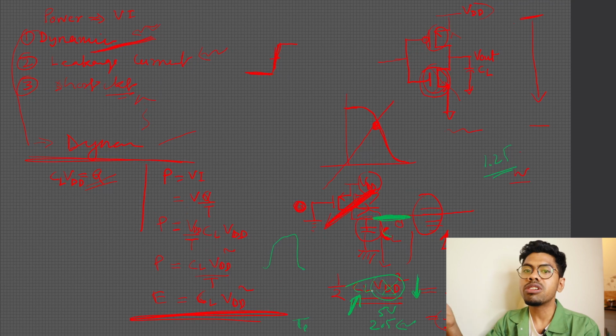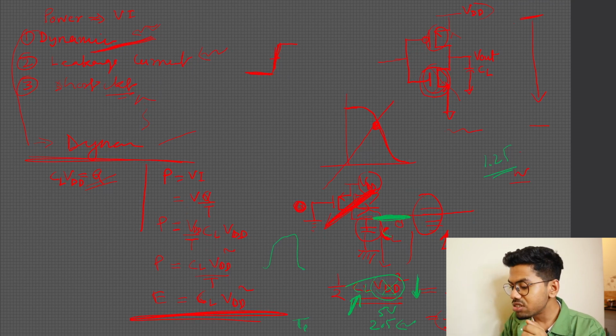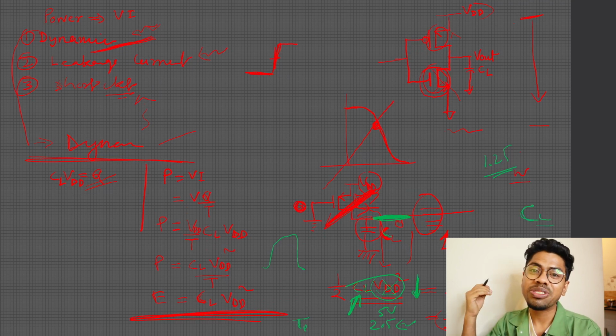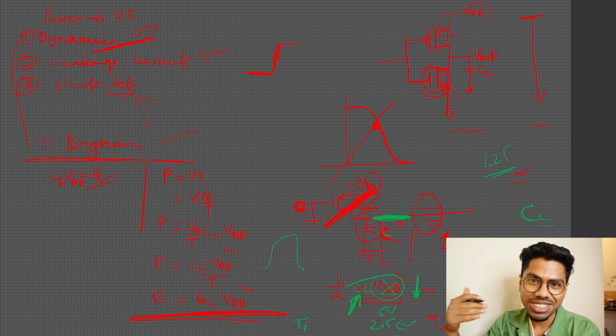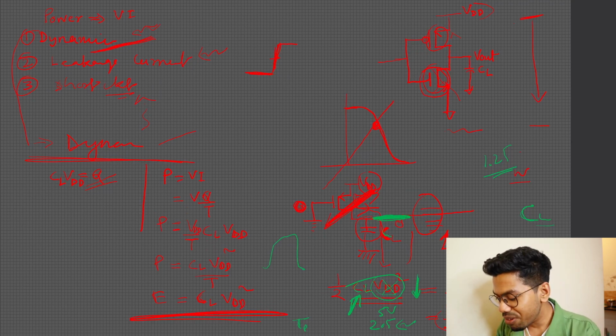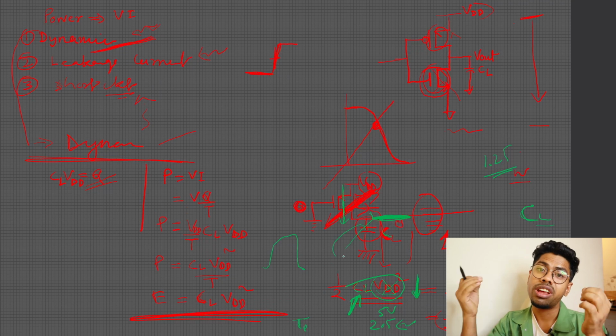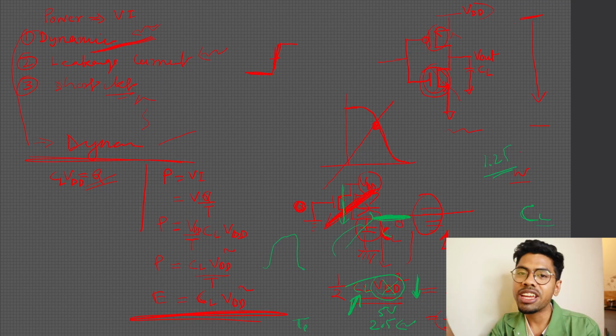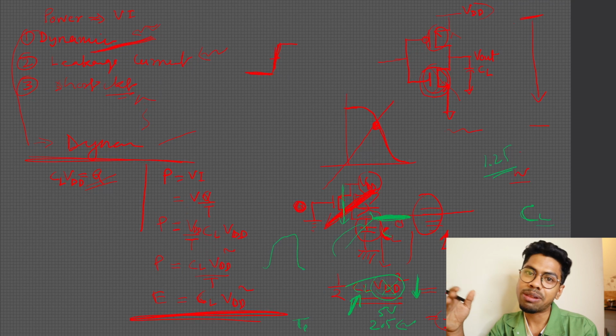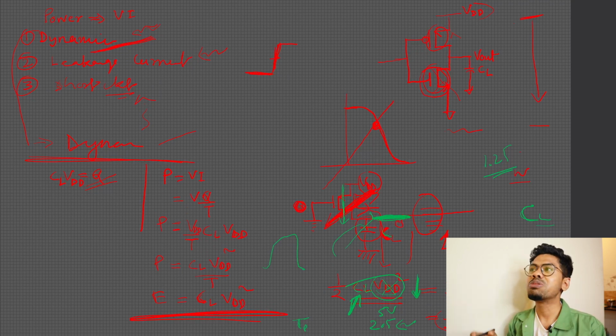There is some other way also, like reducing the NMOS or PMOS size, because if we reduce them, then directly they will reduce our capacitance. But again, this will degrade the performance of your circuit, because the current flow through that device will drop, which implies the charging and discharging time of your capacitance will increase, which implies your TP, rise time and fall time will increase, and your performance will decrease. So there should be a balance between the power saving and the performance.